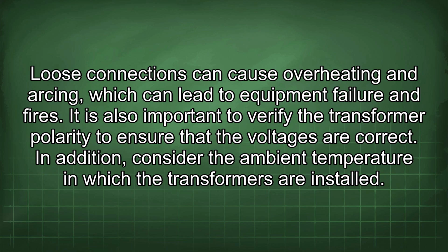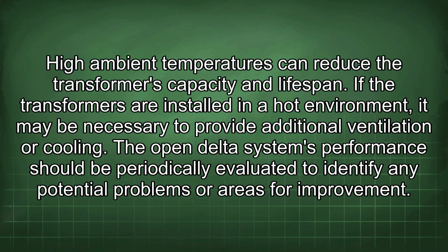In addition, consider the ambient temperature in which the transformers are installed. High ambient temperatures can reduce the transformer's capacity and lifespan. If the transformers are installed in a hot environment, it may be necessary to provide additional ventilation or cooling.